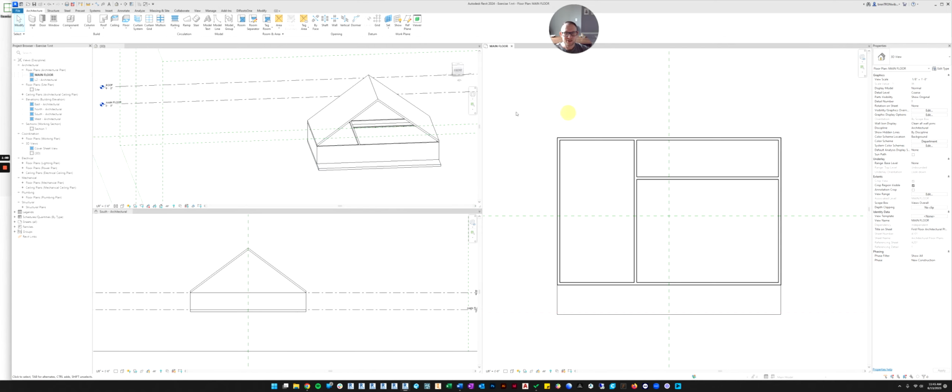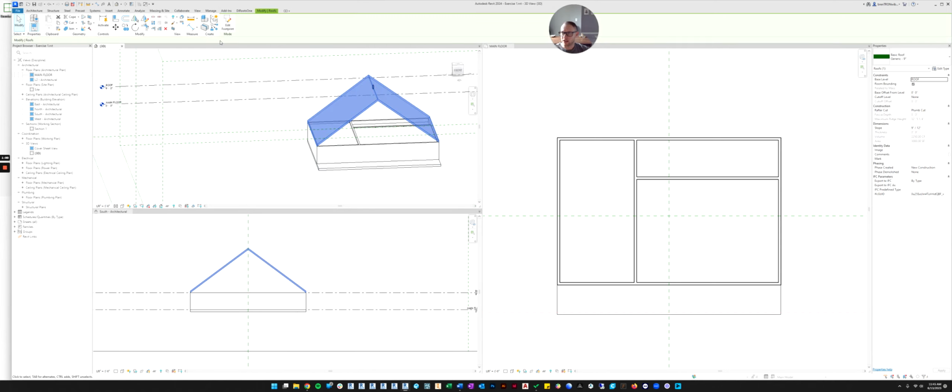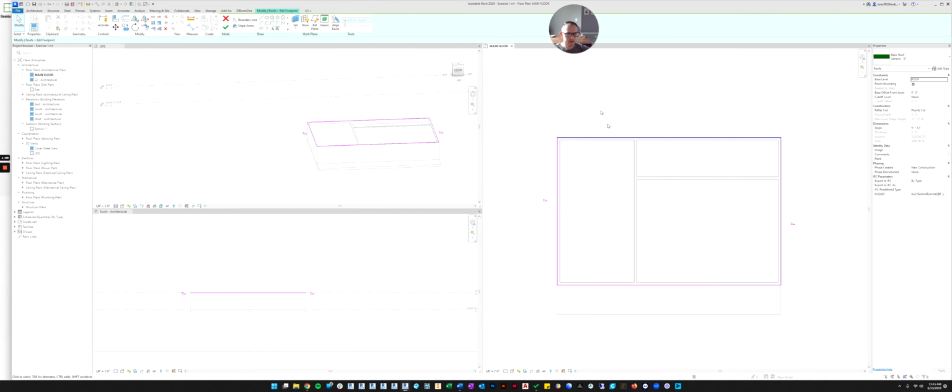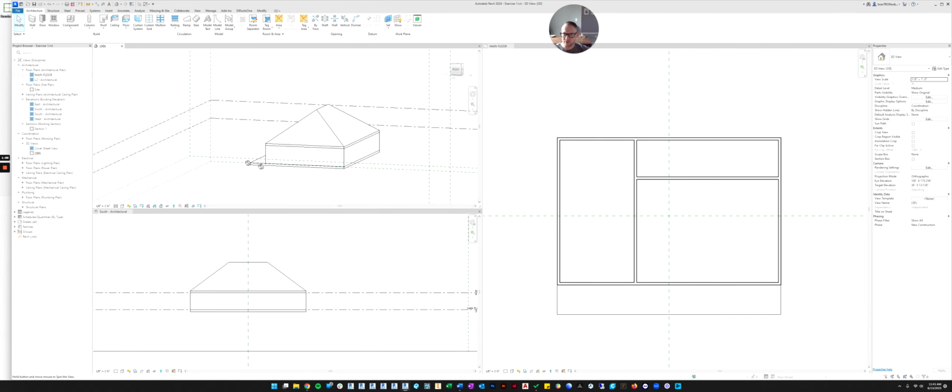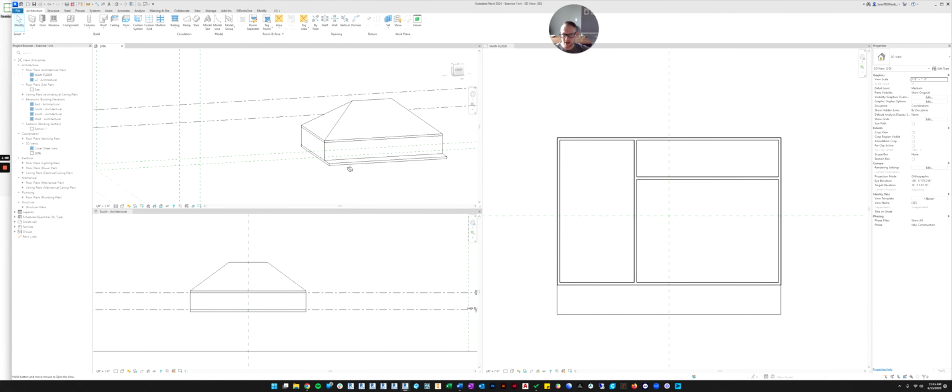Now it makes a big gable at the front of the house, which looks a little bit funny. So maybe let's just angle all the edges of the roof. Let's go back, edit the footprint. Let's put the angle back. Let's select both of these walls, hit define slope, and then finish. And now there we go. That looks more like a normal looking house.